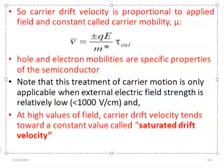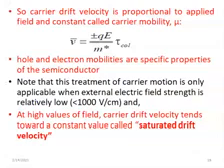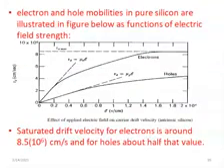If the field intensity is more than that, this formula is no longer applicable, because at such high voltages you attain a point where the velocity becomes constant, and we call that constant velocity the saturated drift velocity. But whenever the field intensity is less than 1000 volts per centimeter, we should expect that formula to be accurate.